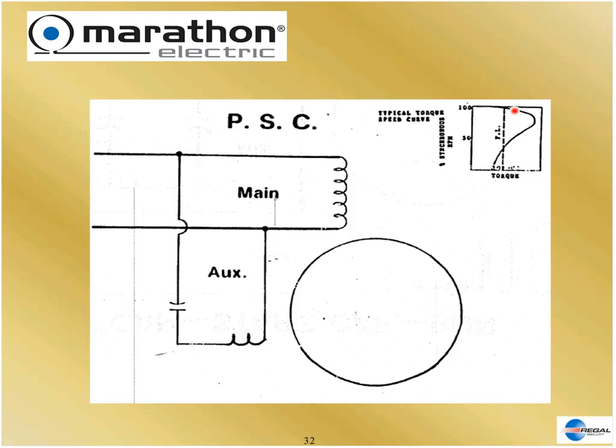What does it do for the starting? It does inverse to what you would like it to do. It does not produce a lot of starting torque. That's by the nature of the beast. It is designed to help the running condition, not the starting condition. But we don't care, because we have a variable torque load which starts here. We don't need starting torque. And when we accelerate, we get good running performance.